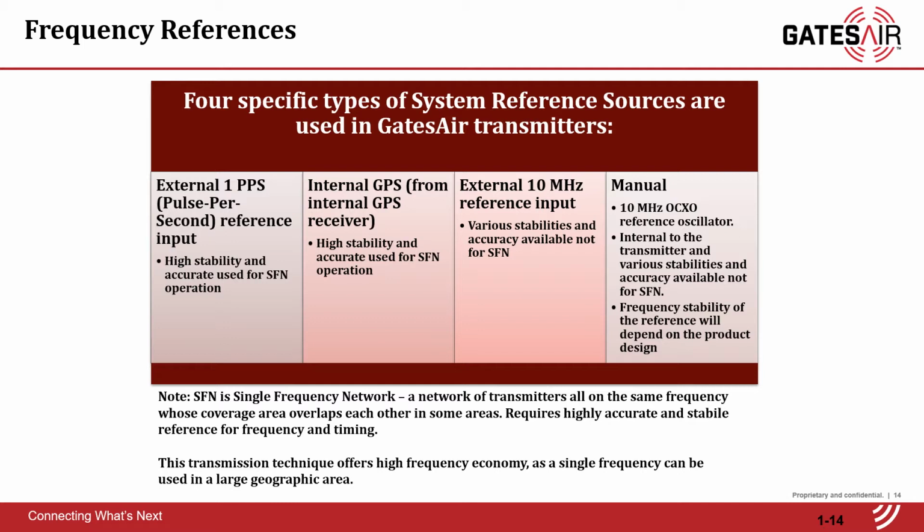This can be used as an SFN, or single frequency network, to cover long odd-shaped territory. One prime example of an SFN is along the California coast. To the west is ocean, to the east is a mountain ridge. There's no need to put power in those areas, so by placing small transmitters along the coast on the same frequency, as a vehicle is traveling up the coast, the receiver would seamlessly switch from one transmitter to the next with no interruption of service.